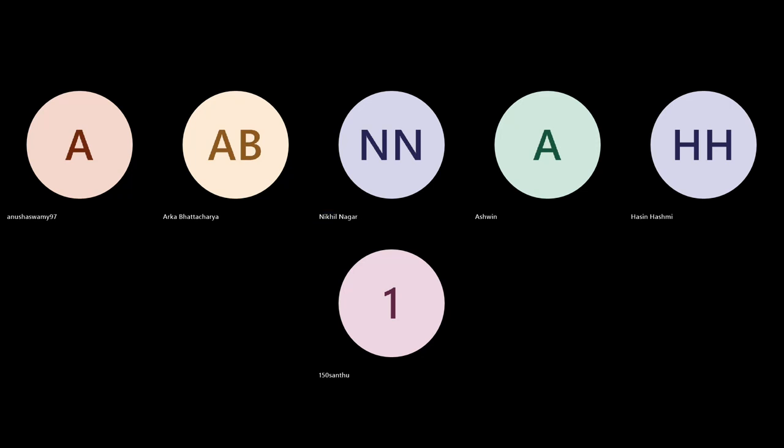So okay, we start. First of all, I take a default building by clicking on structure wizard, select unit, take it in meters, click on OK, and take any frame model, in which we are taking the frame as bay frame. Now I increase some height, like 24, sorry, 24. And the 8 segments, I converted into 15.